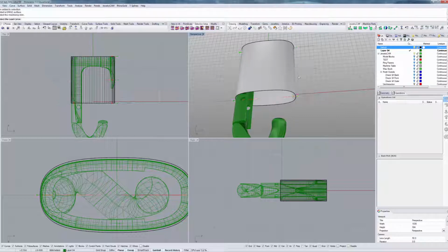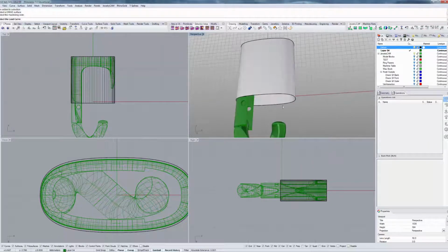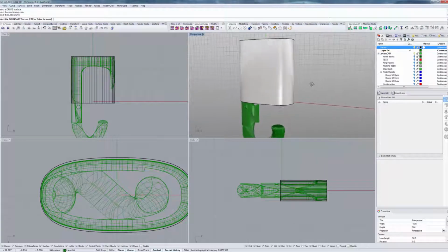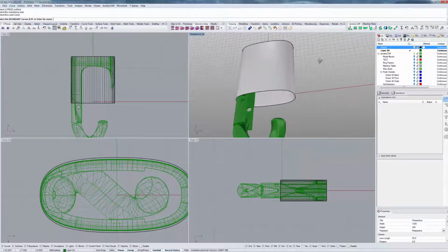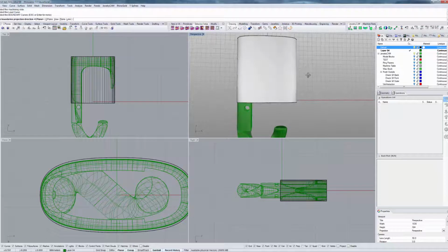So select the outside, and then we're asked for a lead curve, which is almost always the edge of our drive surface. We can also select additional boundary curves, but in this case, we're going to keep this example simple, and we will press enter for none. And finally, we're asked if we want to keep our boundary projection direction at default of C-plane, which we will.